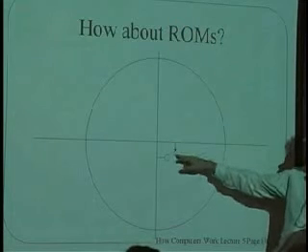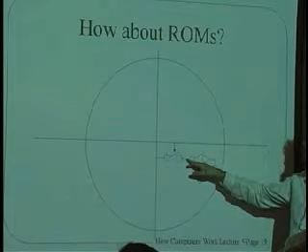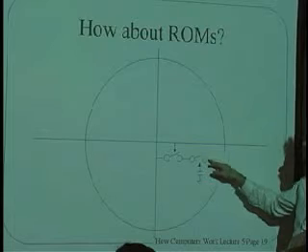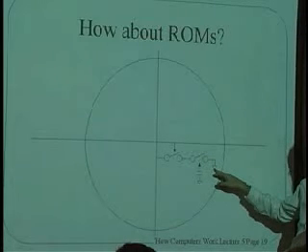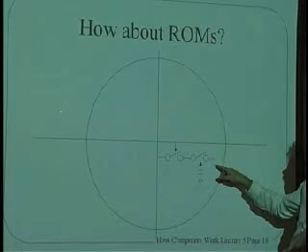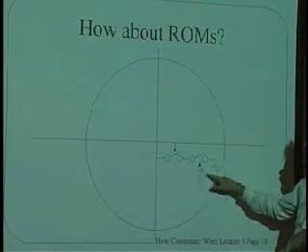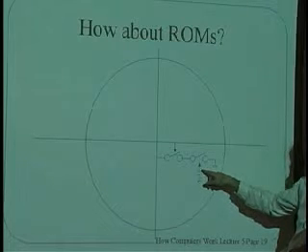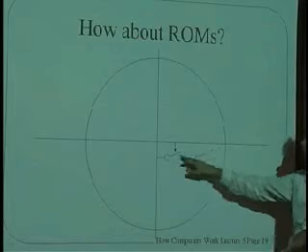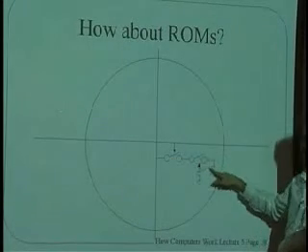The row selects a switch, and that chooses this path here. And this path is not a capacitor, but is in fact another switch, which goes to ground. Ground is the symbol here. Basically, if this capacitor here, which is floating out in space, has charge on it, has energy in it, this switch will be closed forever. And if this switch closes and this switch is closed, then this wire will be connected to ground.